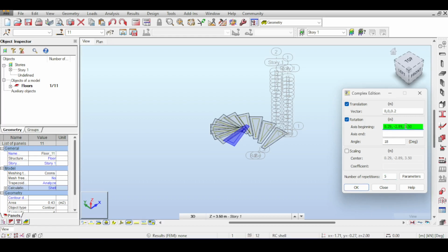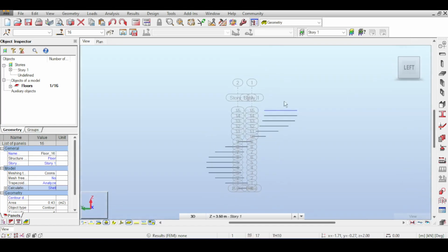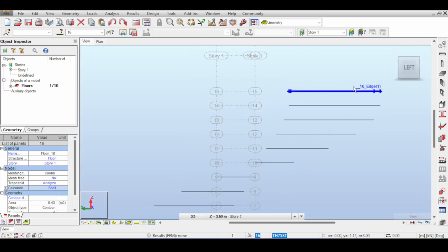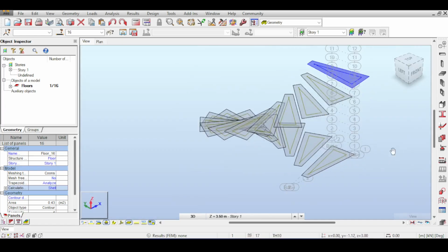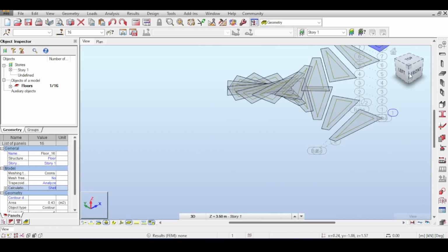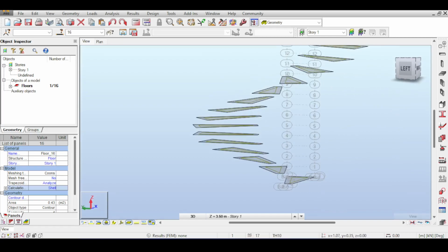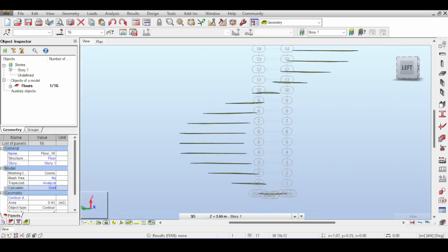My axis is 0, 0, 0. Let me just do this. 0, 0, 0. End is 0, 0, 1. And I think if I hit OK, it will continue correctly, right? Yeah, now I'm happy. Now I think I'm okay. Now it still will weird you out. It reached 3 meters, you can see from the axis. But you see, there is one redundant step because you always start with the ground. So you can actually delete this because this is the ground level and you don't need a step at the ground level.